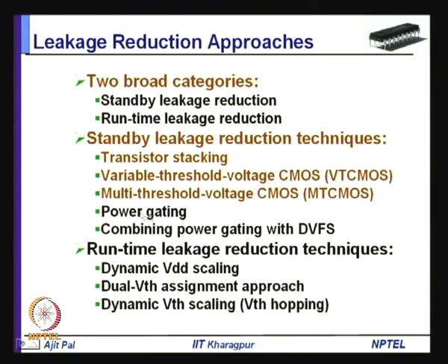In the next lecture I shall discuss this in detail. Then there is another technique, combining power gating with dynamic voltage and frequency scaling. Earlier we have discussed the dynamic voltage and frequency scaling technique, which can be combined with power gating to reduce standby leakage power, which I shall discuss in the next lecture.